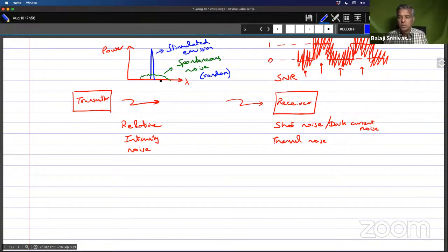So both of these are emitted, and it's inevitable, right? Whenever you have a laser, you are primarily getting stimulated emission, but it's inevitable that you have a little bit of spontaneous emission also. And that spontaneous emission has a random phase, so when it beats with the stimulated emission, the beat component will be quite noisy, because the phase can be the same, in which case the photons add and the strengths of the fields add, or it could be out of phase.